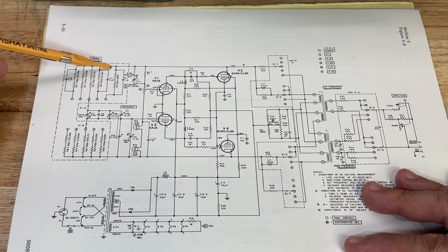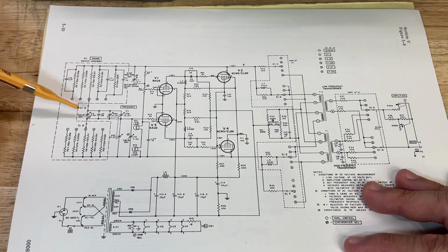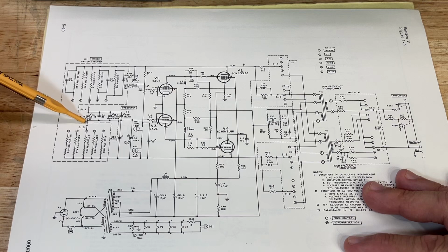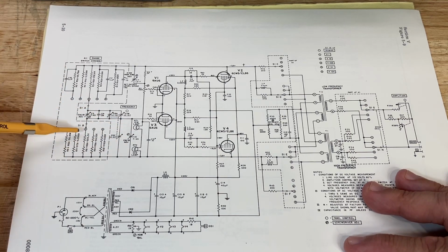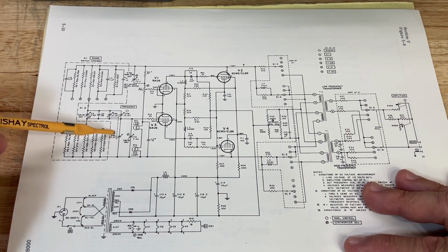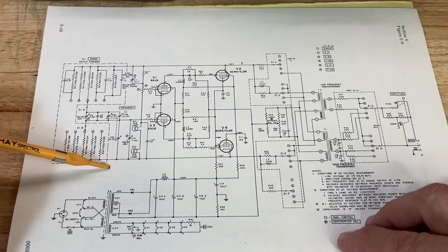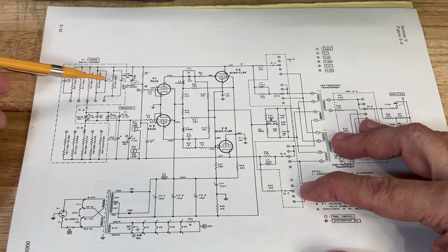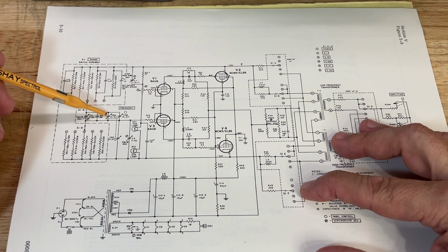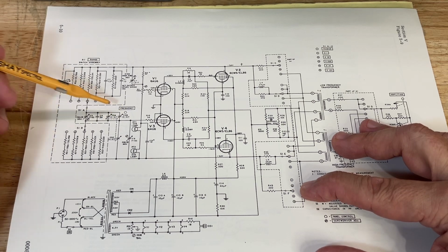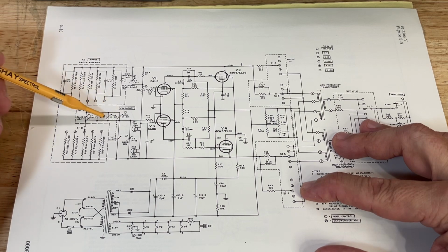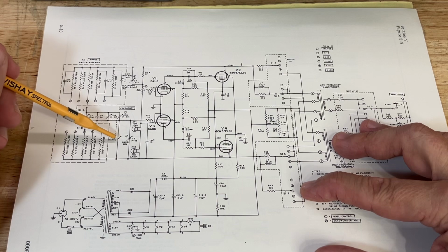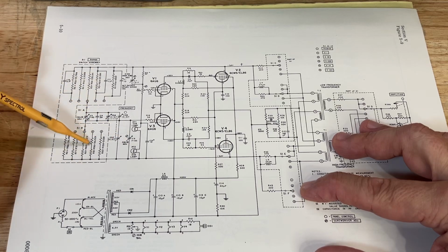You can see here is the series resistance and capacitance in the series part of that positive feedback leg. Here is the parallel resistor and capacitor combination, also in the positive part of the feedback leg. You'll see in the 200CD that there are actually two sets of tuning capacitors in parallel with one another in this series leg, and only one capacitor in the parallel leg. But the resistors are opposite. So this is half the value, and this is twice the value.